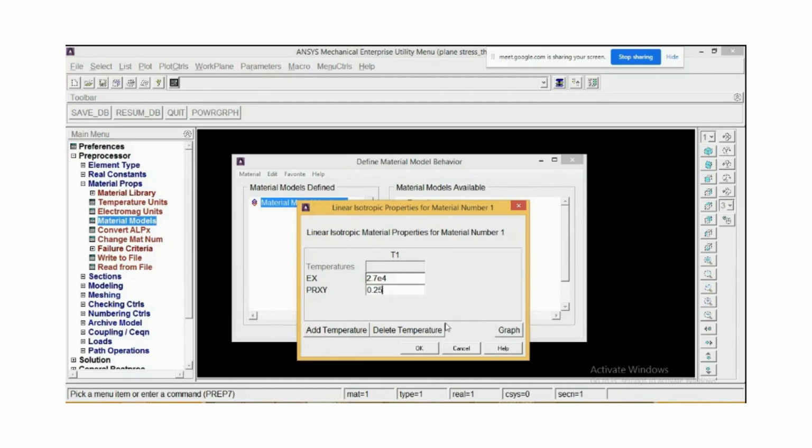For the retaining wall, RCC properties have to be used, right? You cannot use steel. You can search for that Young modulus, you can Google it, or you can find it in any civil book. As the material changes, right now the material for the retaining wall of the dam will be RCC concrete. So you have to select appropriate values of material properties.